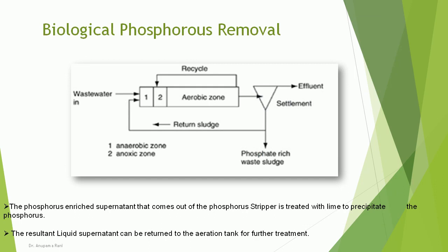Coming to phosphorus removal now. Normally secondary treatment can only remove 1 to 2 mg/L of phosphorus, so a large excess of phosphorus is discharged in the final effluent, causing eutrophication of lakes and natural water bodies. Generally it appears as orthophosphate, polyphosphate and organically bound phosphorus. Phosphorus is required by microbes for cell synthesis and energy transport, maintenance, and it is also stored for subsequent use by microbes.